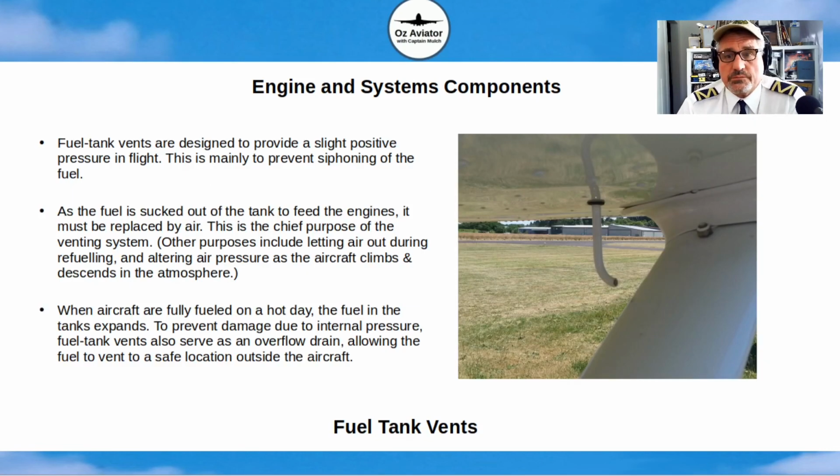Fuel tank vents. So fuel tank vents are designed to provide a slight positive pressure to your fuel tank during flight. One of the main reasons is to prevent fuel siphoning off, because the way aircraft wings operate is that there is an area of low pressure over the top of the wing which could lead to fuel siphoning. So the fuel tank vents are there to help prevent that occurring.